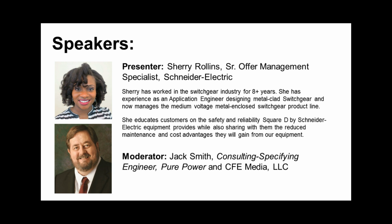The failure modes, and by the way, what I'm getting ready to mention is extremely rare. But over the life of the breaker, you could potentially see tripped coils, closed coils, or motors that would need servicing. And what's the big advantage of fixed-mounted switchgear? Every one of those potential modes of failure is completely addressable from the front. So you do not need to remove the breaker. You just have to remove the front cover, and you can service all those items from the front without removing any components. That's the first advantage.